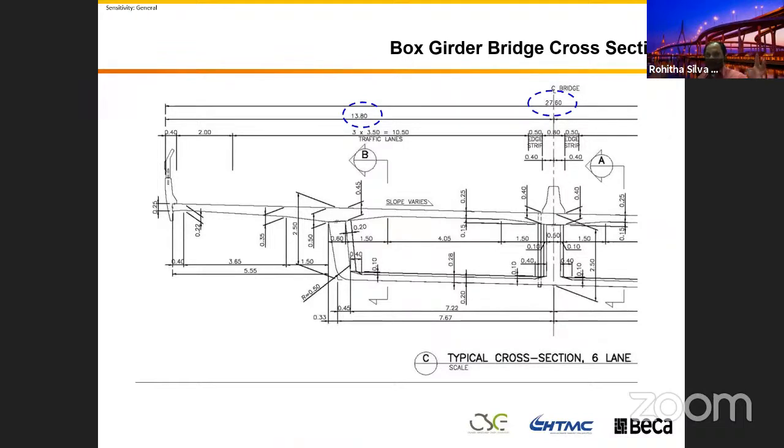It's one big unit. And the cantilever section of this bridge is 5.5 meters. We call this one the twin cell box girder because I put only half of this section for you to understand. The depth of this bridge is 2.5. We're going to span 48.5 meters. It's a massive bridge, right? So before, you would try to build a 13-meter wide bridge using a series of I girders, right?